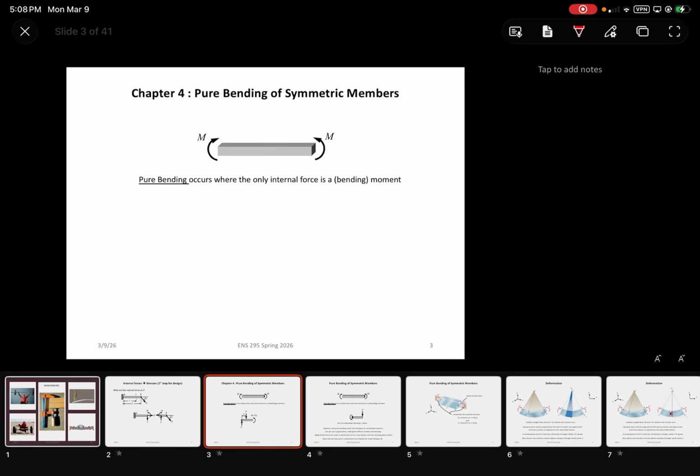We'll learn how to draw these diagrams later on, but you could think of it like, let's say we have a beam here subjected to force F located at distance a from either side. That region within the beam would be subjected to entirely pure bending.